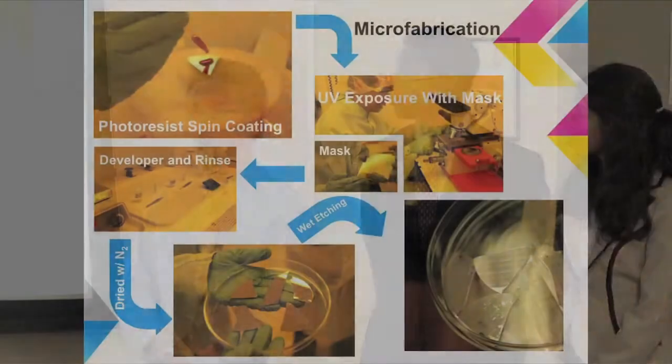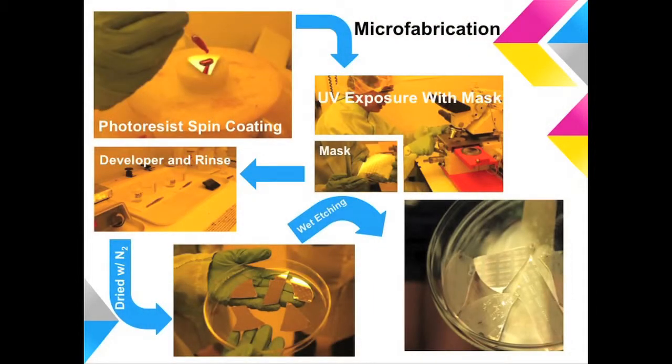The first two steps in SAW device fabrication are sample cleaning and electron beam physical vapor deposition. Due to time constraints, these two steps were already done for us, so we just started off with 5 aluminum-coated clean samples. The first step we did was spin coating.